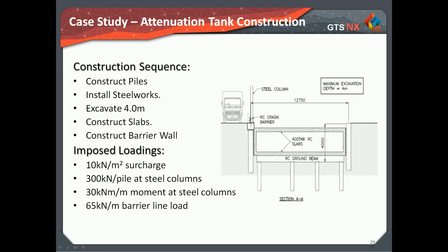Here is the construction sequence and imposed loadings. Analyses are carried out to compare the main factors of wall bending moment, wall deflections, prop force, or in our case slab force, and time spent on modeling and analysis. As I mentioned earlier, there are also some field data available from surveying the top of contiguous piles for lateral deflections during excavation, which are compared to the theoretical results.